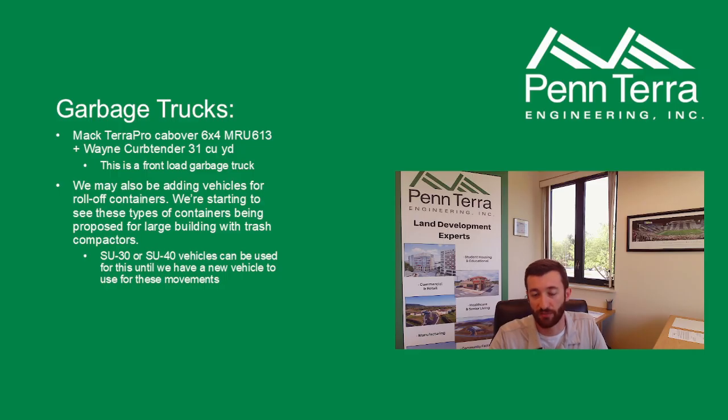We may also add some vehicles in the future for roll-off containers for refuse. They're starting to be used on large buildings that have trash compactors, mainly downtown, or we've used it on Toftrees West. Right now, in place of the specific design vehicle, we can use box trucks. They're pretty similar to the roll-off type vehicles. An SU30 or an SU40 would work for this.